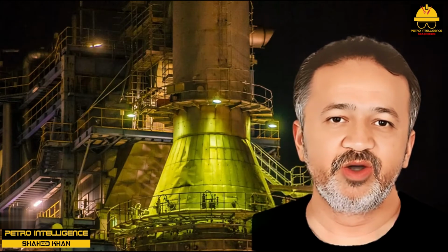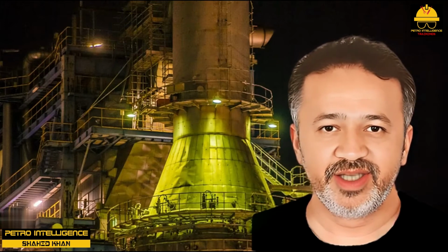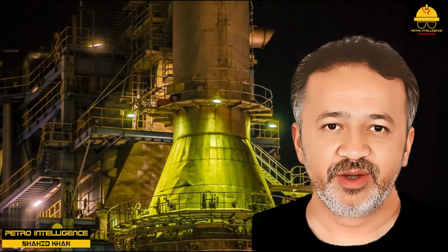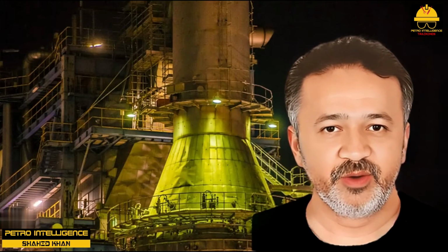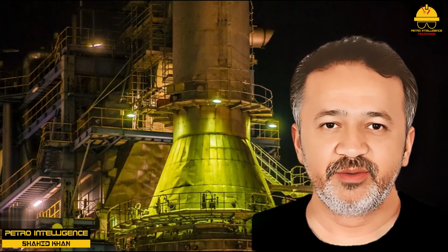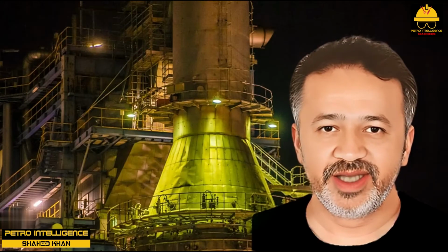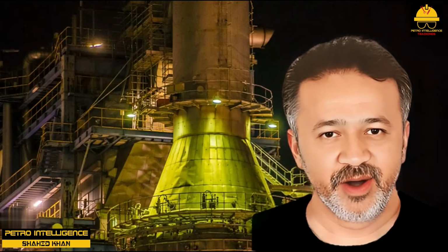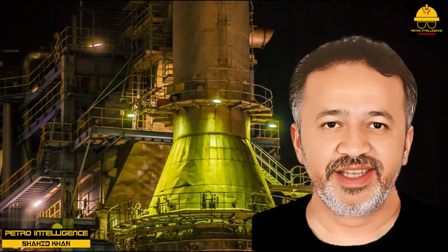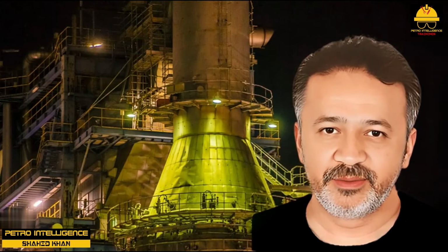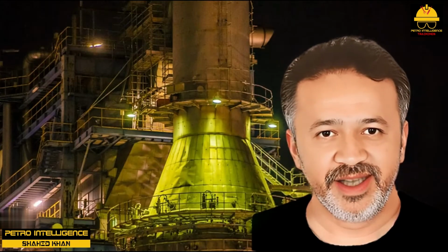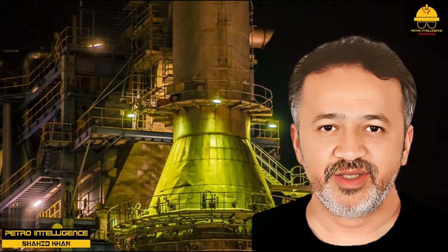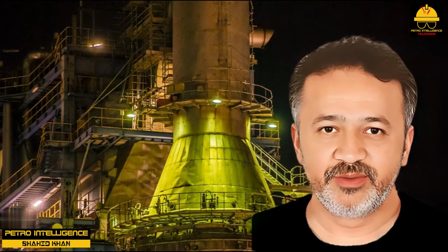This heater, which was also manually operated, had an oxygen analyzer probe installed in the convective section. The operators were given a target range to run between 2 and 6% O2. Note that this range would in many cases actually include the point of absolute combustion. The inside operator, Operator A, noting that the stack gases had 8% O2, began to cut back on the combustion air. As Operator A pinched back on the air register, the convective section oxygen dropped slowly from 8 to 7.5% O2.